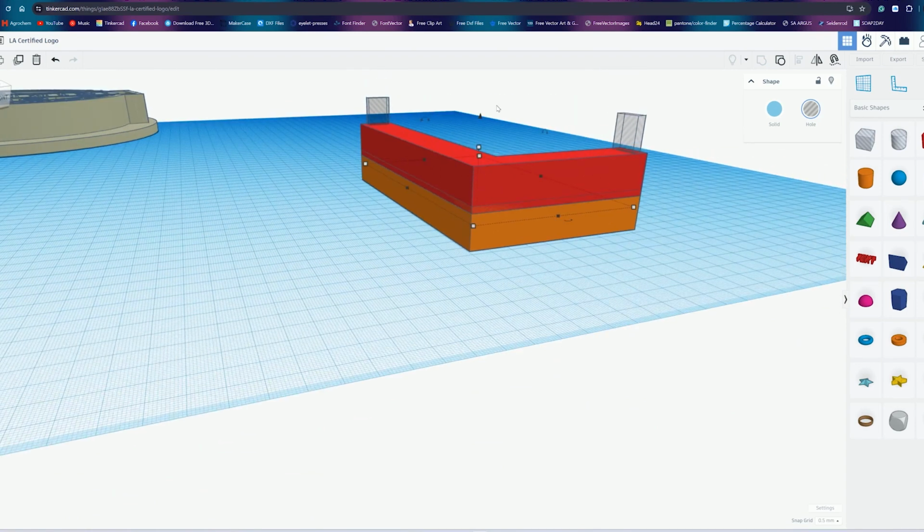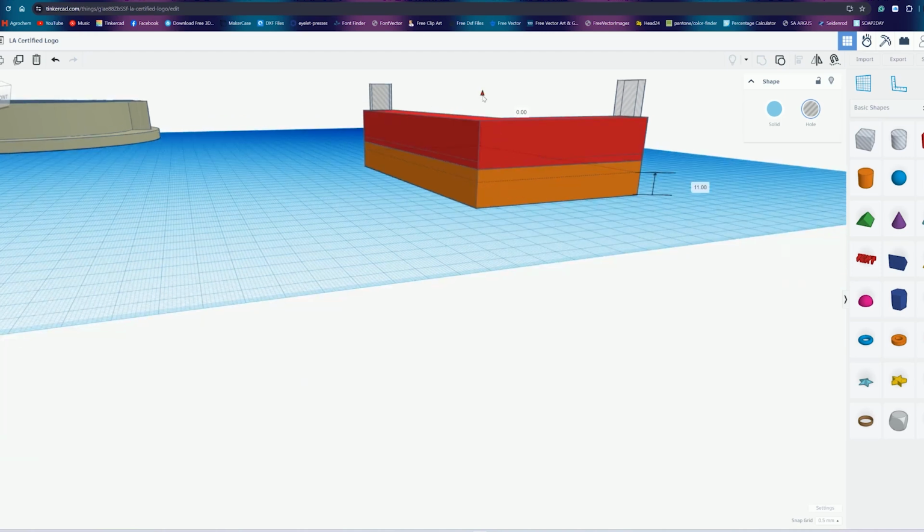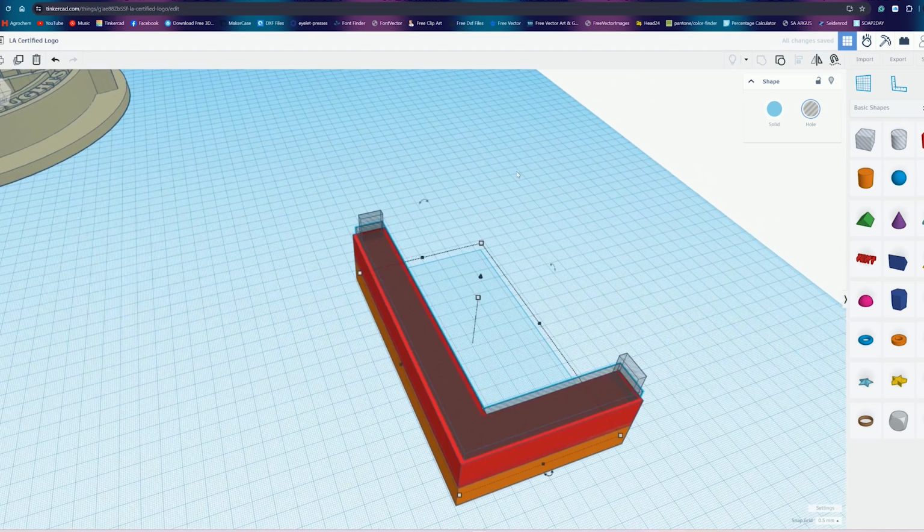And I think that you should leave yourself at least around a 4mm base so that the letter is strong, and then you can start your crop from above that. So let's go ahead and move this to about 4mm above. And actually, sorry, we're going to go 6 because we're going to make this smaller, half the size. So that'll be a 3mm base. So we'll go from there, and then we need to increase the size so that we can see it being punched out all the way.